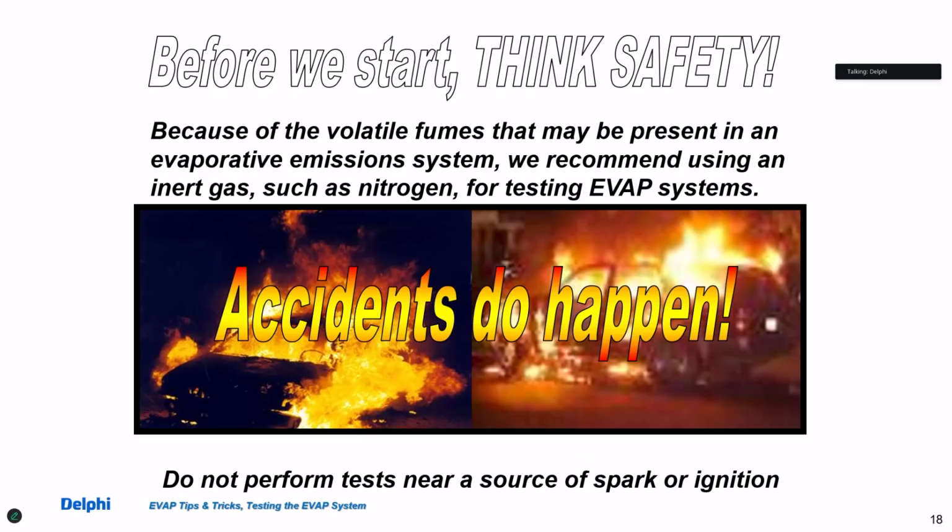I'll show you an example of what happens if it gets into a closed system and there's a spark. It'd be just like a combustion chamber. But do be aware that there are some safety issues involved in this. If you did a Google search, you'd find there are a couple of incidents around the country, and in Canada, where shops were burned down because of EVAP fires. The vapors got outside, there was a spark, and bang, there was the start of a major fire. So all we need is a source of ignition when we're working with EVAP.